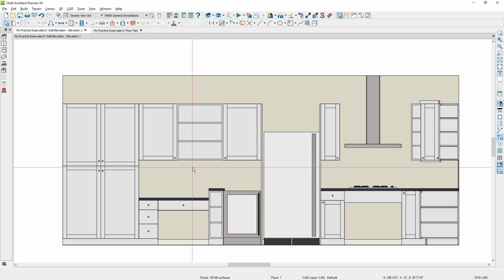Now if you notice my cabinets, one of the things that I did not do was define my default cabinet to have moldings. Now when we created the molding, and you can see it over on the corner cabinet, you can still see the molding on it. You can select all of the cabinets and add molding to it. You'd have to remember what the offset was, what the size of the molding was, and it's very easy to do. There's also a tool called the Object Eyedropper.